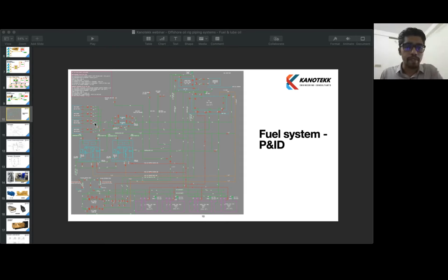Yes, there is a question. Leak from fuel oil lines back to fuel tanks or dirty oil tanks. Any containment fuel oil spilled will flow to dirty oil tanks. We will not be taking it back to fuel tanks. It will go to the dirty oil tank because any dirty fuel which goes to fuel tanks can contaminate the storage or day tank, whichever tank it is pumped to.